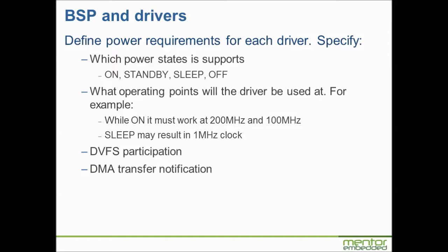So what we need to do is to look at each driver and to look at its power management requirements. First of all, we need to look at what power states it supports. So possibilities here are on, that's kind of obvious, and off is another obvious one. But there may be low power states the CPU can be in, like standby and sleep, and we'll talk a little more about those in due course. But are these supported by a particular device, and hence does the driver need to be informed accordingly?